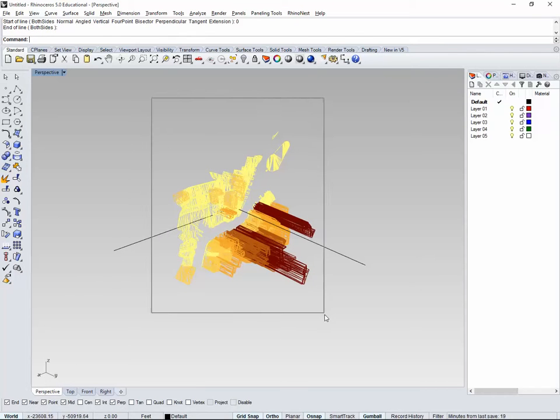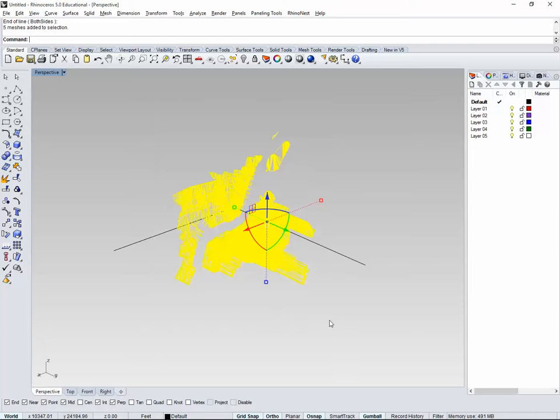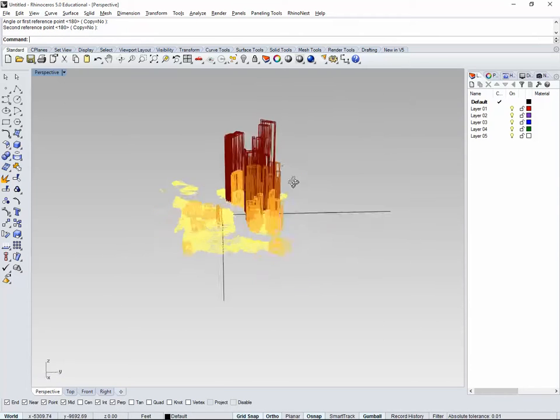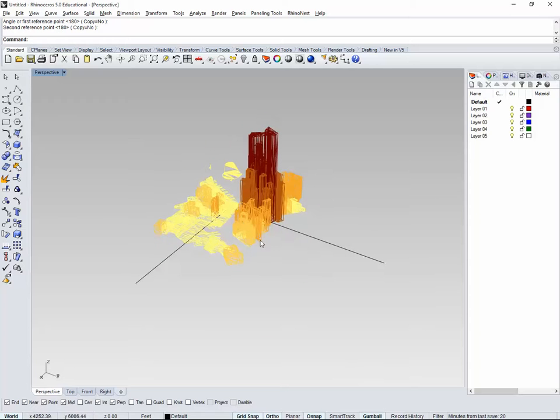Next step, I'm gonna select all of our city extrusions, and we're gonna rotate 3D. Okay, I press enter. I'm gonna press 0 again, so we start the rotation from there. Now, if you have the ortho, you need the ortho here. You need to click once on this axis, another one on this axis, and then another one upwards. Okay, deselect, so you make sure that the city is looking up. This rotation needs to happen for every single diagram that comes from GIS.